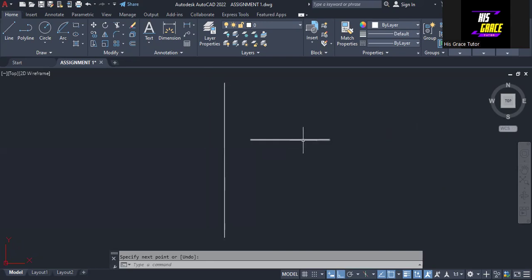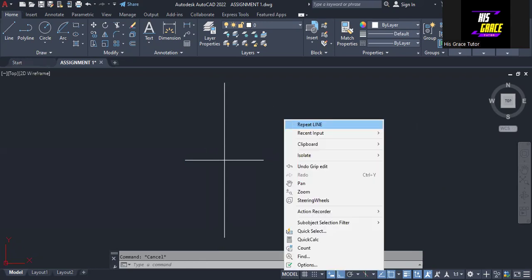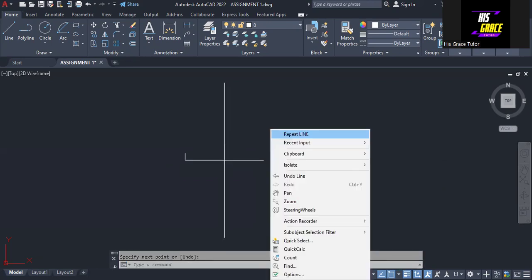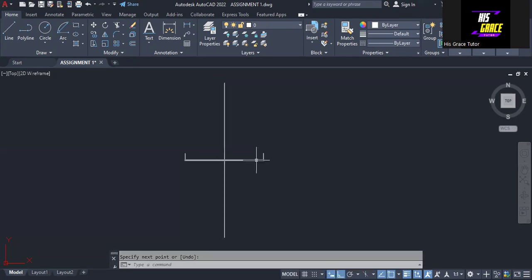So we are going to select this line, and then we bring it to the middle of the vertical line. So we have this, so press escape key on the keyboard, and then the next that I'm going to do is that I want to make sure I mark these points. So just draw a short line at this point and repeat it here. So draw a short line at this point. Then I'm going to extend this line to the right and also to the left side, any length. So press the escape key.